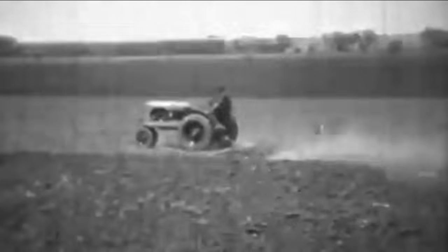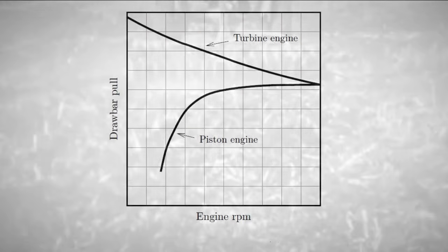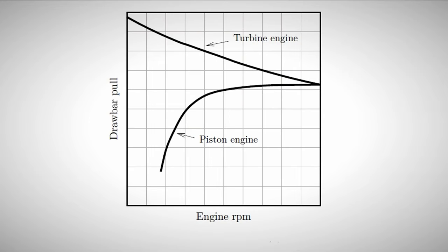Among the other advantages of the free-piston engine, the designers were attracted by its very high torque flexibility, or engine flexibility coefficient. This was important for a tractor. This torque reserve helps the tractor overcome sudden, short-term overloads during operation without stopping or shifting gears. The traction curve graph shows that with increased load and the resulting reduction in engine speed, the towing capacity of a piston tractor decreases, while that of a gas turbine tractor increases.